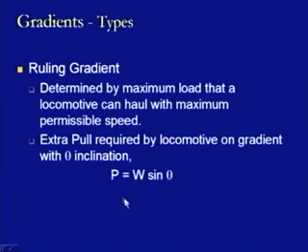So, in this case this extra pull will be defined as P equals W into sin theta, or this sin theta, because theta is very small, can also be transformed into tan theta, and when we transform into tan theta then it is nothing but the gradient, because the gradient is generally defined as say 1 in x, and 1 in x is nothing but tan theta.